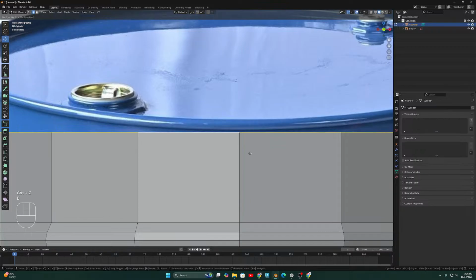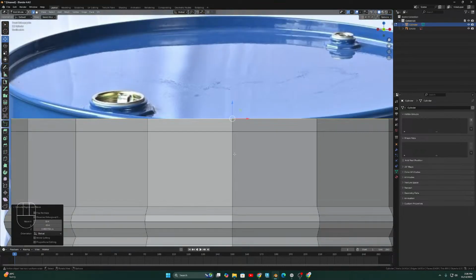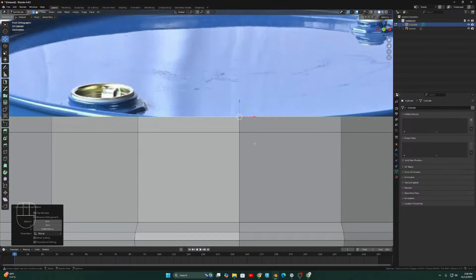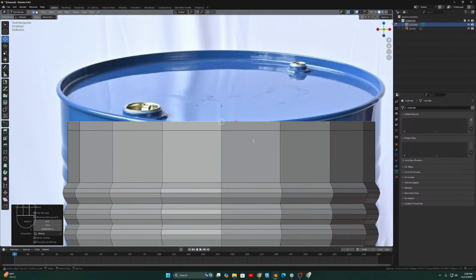If I press E and then move, it will get extruded, but again you will have to be cautious about the axis. Now it has this much depth, and that is very sharp and straight, and this region is having some extrusion outside like these shapes, but it is also very sharp.